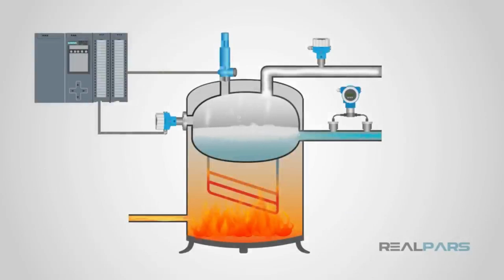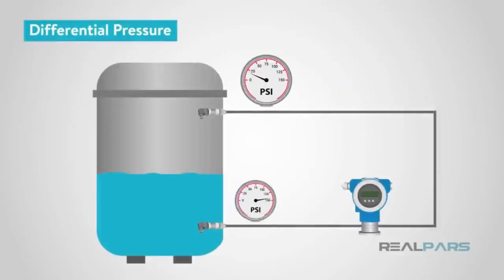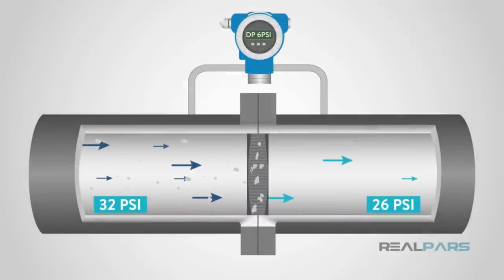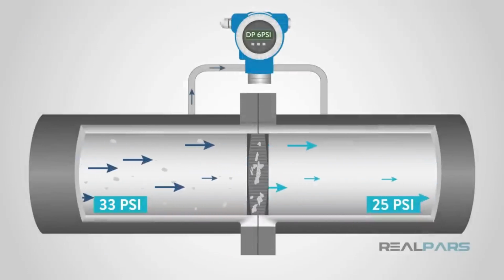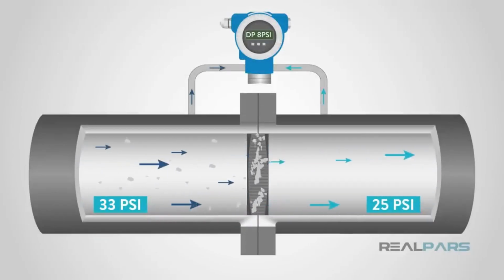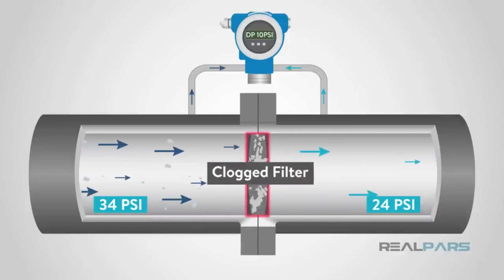Pressure sensors are commonly used to monitor pressures in different processes. A common thing to monitor is steam pressure. That pressure sensor can be used to control a valve to keep steam pressure at a constant level. Another common but lesser known use is to monitor the level of a liquid in a tank. Filter clogs are a common use of differential pressure monitoring. By knowing the pressure before and after the filter, you can determine if it is clogged.